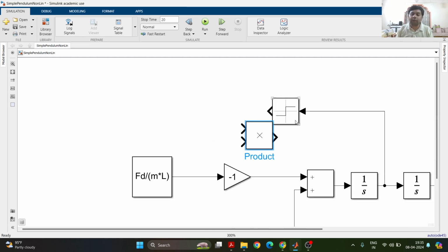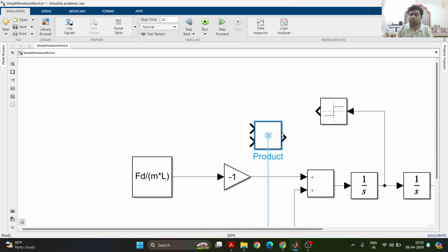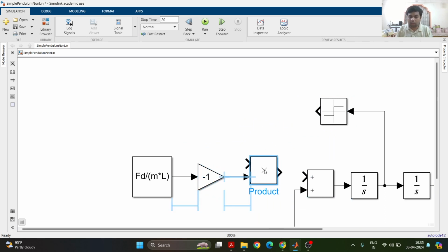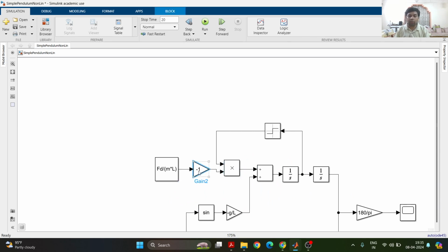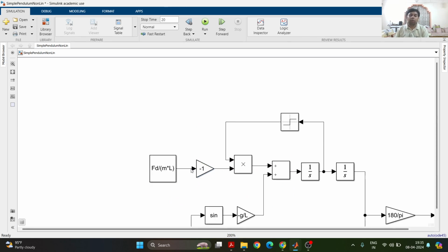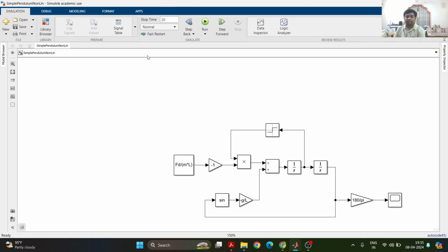And then we'll multiply this sign, so this is our actual damping force. The damping force will be opposite to the velocity by using this concept. Here we are getting the angular velocity, and this is finding out the sign of that, and then we are introducing it here this way.